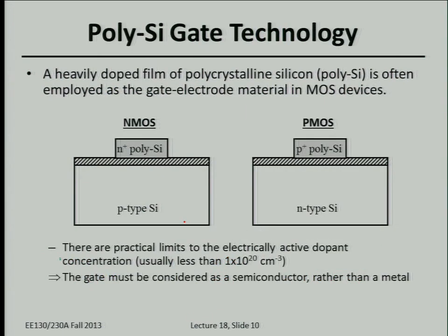Okay, so the final topic, not quite final, but almost, is gate depletion. As I mentioned, heavily doped polycrystalline silicon thin films can withstand very high process temperatures, and that's why they were preferred for CMOS technologies for a few decades. But in reality, during the fabrication process, we really cannot dope it much more heavily than 10^20 per cm^3. It's just practically not easy to do that.